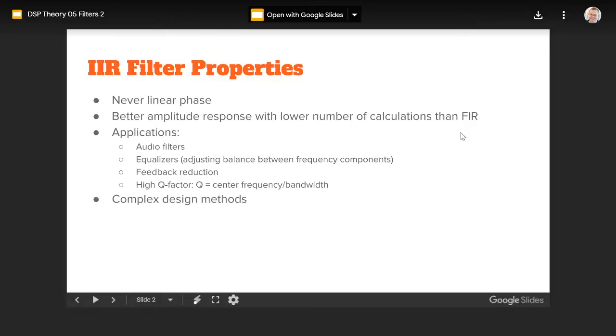So actually this is quite natural, since in case of the FIR, if you take a look at the zero pole plane, we have all the poles at the origin, and we are just using these locations of zeros to tweak the amplitude response. To flatten the amplitude response, we need to add some extra zero pairs like that, not just the complex conjugate pairs, but also reciprocal pairs.